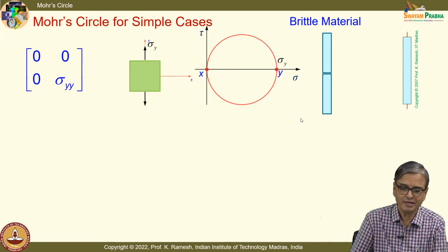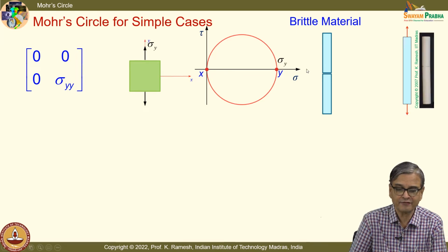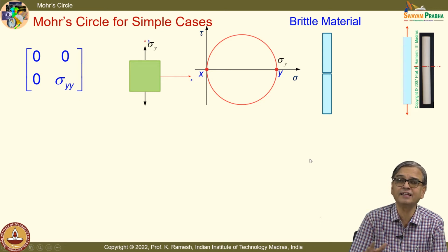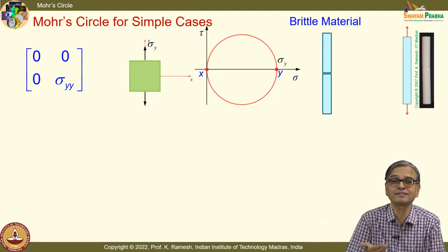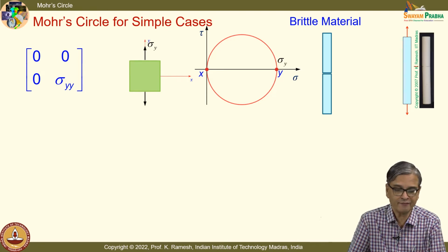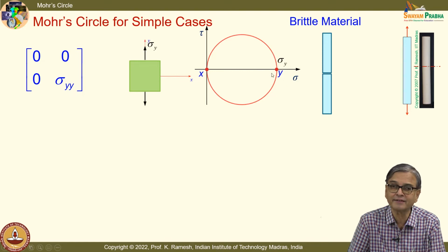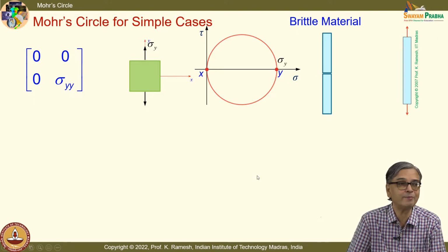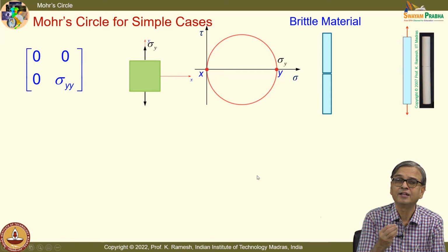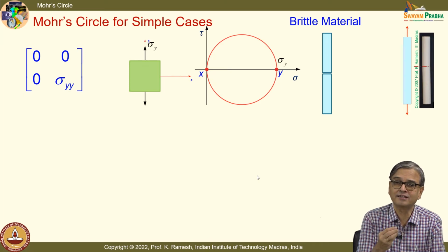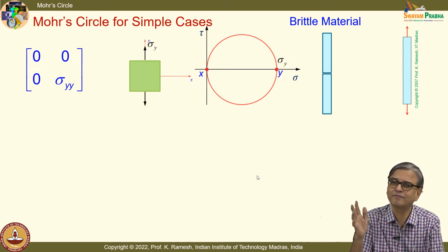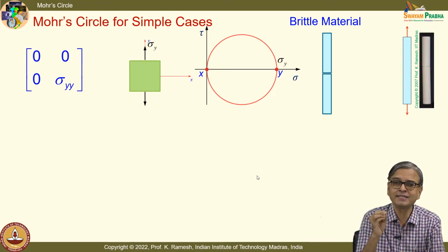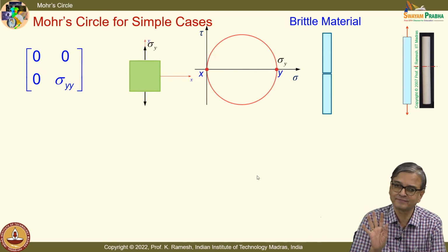The y will be plotted away from the origin, and at some point when it becomes critical, which is the critical plane? We have said wherever you have the maximum normal stress, that is the critical plane. And from the Mohr circle, it is nothing but the y plane. So, the y plane is this. So, you are able to explain from the Mohr circle what is the plane in which you could expect material separation. For chalk being a brittle material, it is straightforward. Fine.